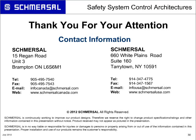If you open up door number 1, the second contact still opens up, shuts the machine down, shuts your motor down, but the first contact never opened up. So the safety monitoring relay sees a closed loop on that first circuit, and when you close door number 1 again, the safety relay says, I don't want to start because I detected a failure.